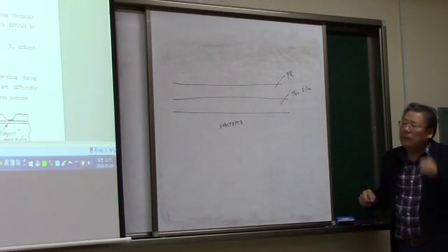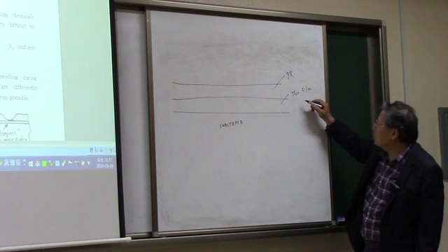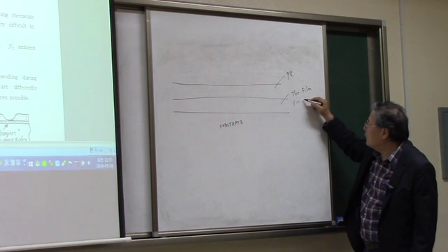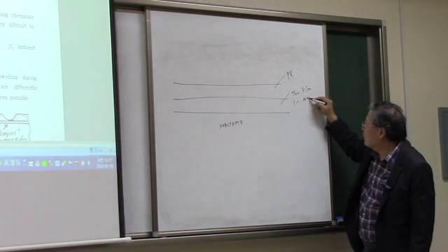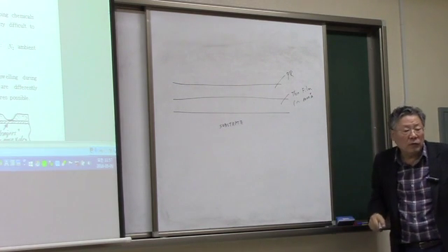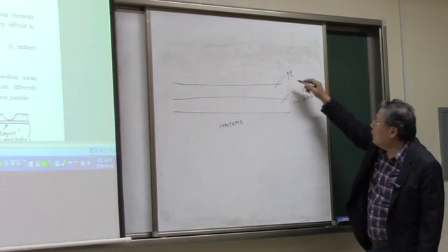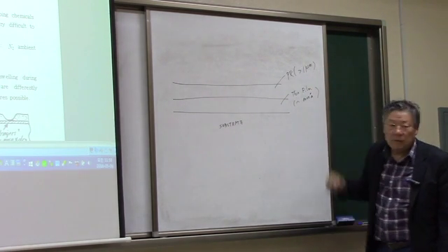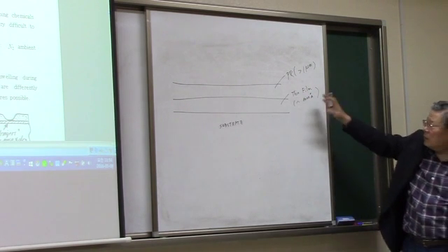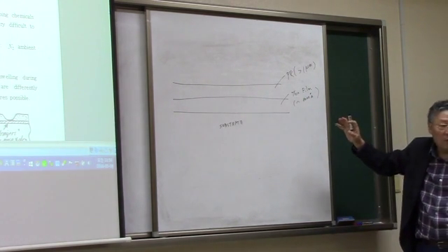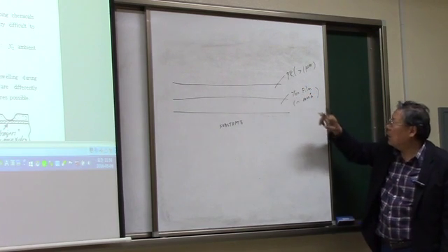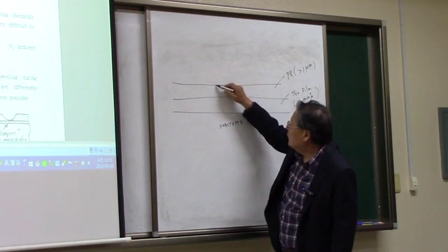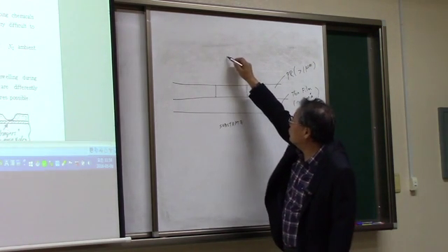Well, for the dimensions that we are talking about, the thin film should be about 1,000 angstrom, okay? 1 or 2,000 angstrom, something like that. The PR is more than 1 micron, usually. So you can have a relative figure of how thick we're talking about here, the PR and the thin film.